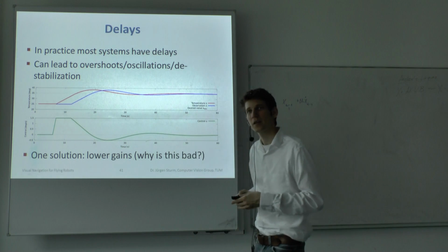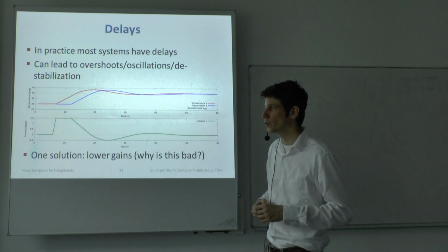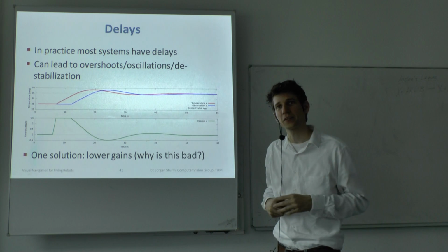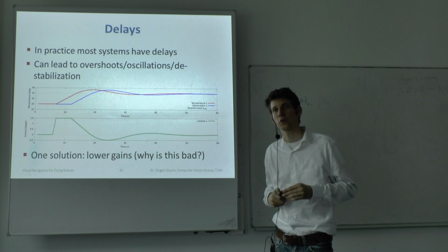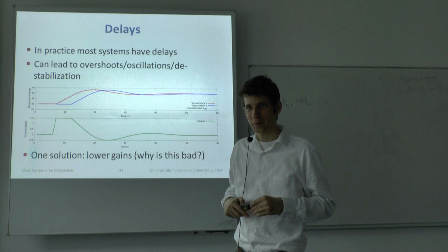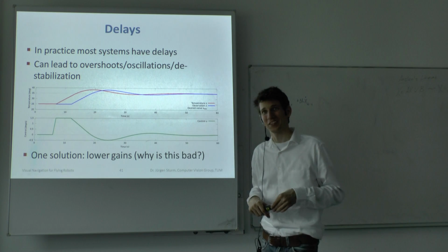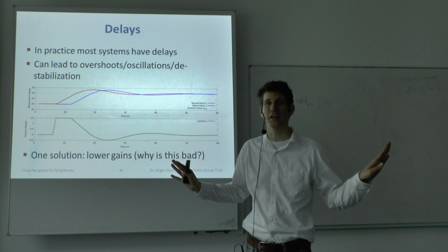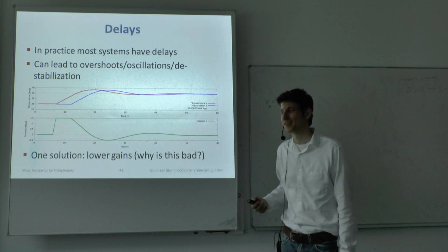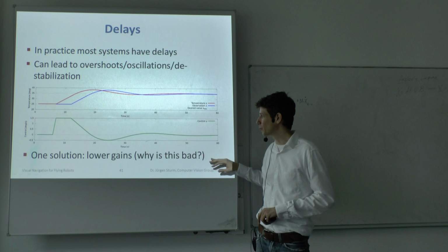What is normally the delay for the quadrocopter? It depends on different things. Normally between 100 milliseconds maybe or 200 milliseconds, in this order of magnitude. Is it because of the measurement, the sensor, or because of the real model? Unfortunately, both. In the real thing, you always have all kinds of noise and all kinds of delays, and even not constant delays, which makes it even more complicated. But I will show you more details on the quadrocopter in a second.